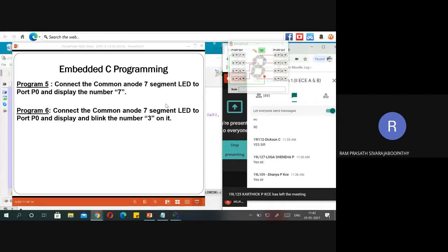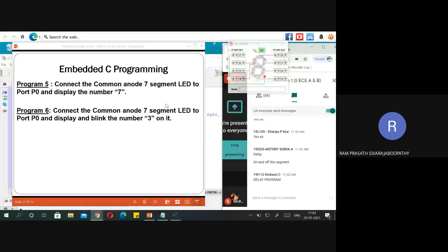In the case of the 6th program, what can we do? Yes, we have to include a delay. So write the delay function, write the value, call delay and put it in a loop. That's a blank we must do. Fine? Okay, wait a minute. It's fine if the delay function is already written.